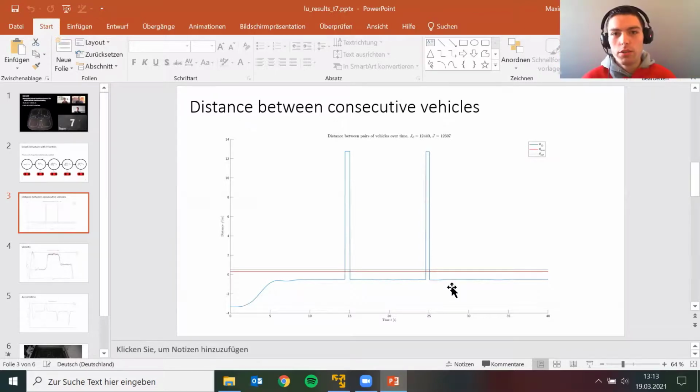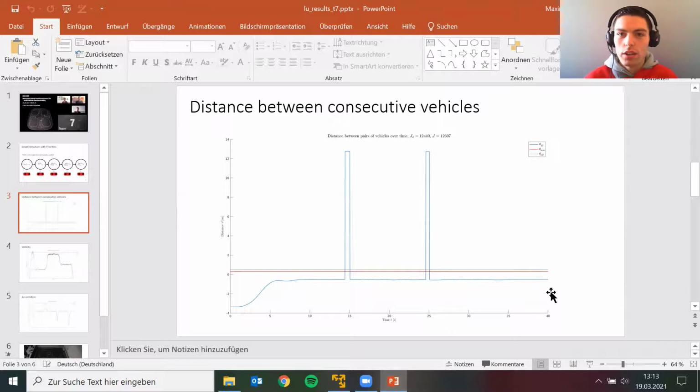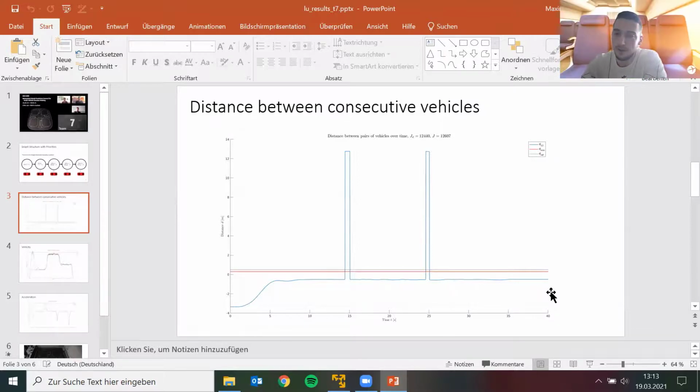I mean, maybe did you put high numbers in your penalizing matrices or something? Yeah, this could be the case. So we played around a little bit with tuning and just tried some different weights. This could be a good explanation. Yeah, actually yes. And what numbers did you put? I guess we penalized errors on the distance tracking by 1,000 or maybe even more.